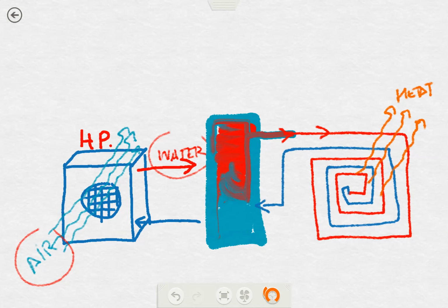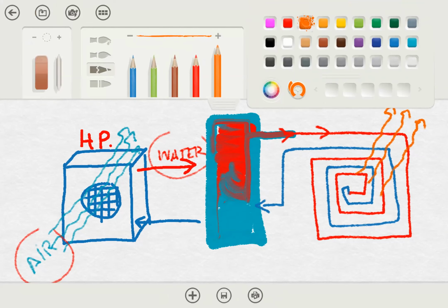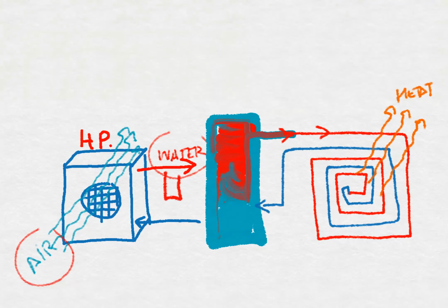What else did we have? We had expansion tanks. Okay, so the expansion tank is something that, well, we need expansion tanks always here. Okay, when we have a closed loop, we would need an expansion tank. So I would place two expansion tanks here.